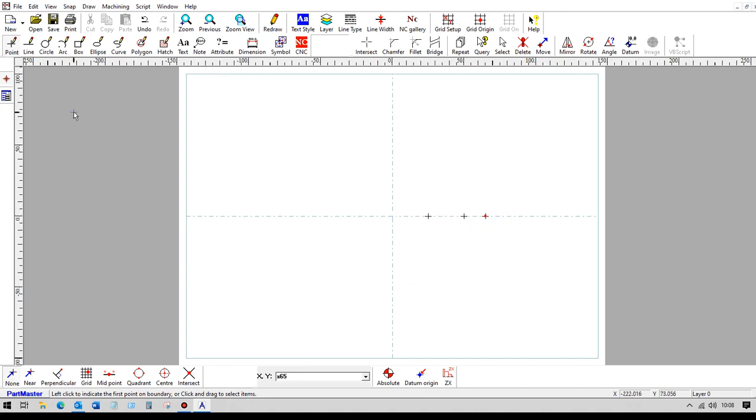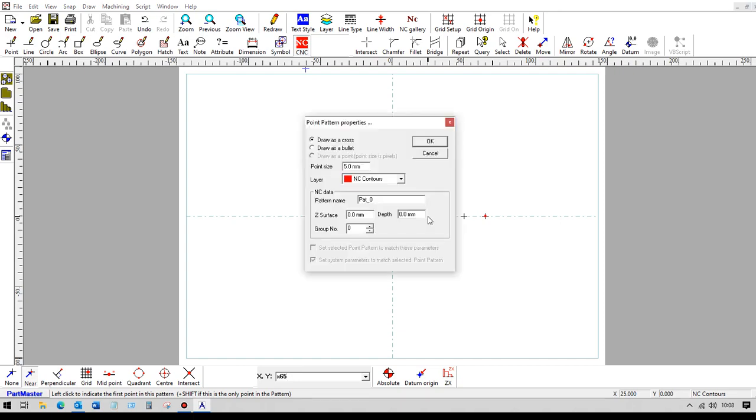So we'll stick with those three holes, and then we'll create a pattern. So we go into NC, the datum there, so this is going to be the end of the bar and the holes will be coming this way. If you're going the opposite way, then obviously the holes will be over here. So we need to create a pattern. So we're creating a pattern, and we need to indicate the first hole in the pattern. So this creates a drill hole pattern.